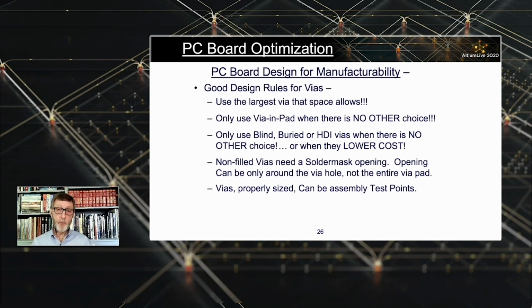We used to spend weeks after prototyping putting test points in really high-density boards at L3 because we knew that before we shipped that thing for final production runs we needed to have 100% test point coverage. If you can't do that, well, I'm sorry. You can't be guaranteed it's going to function. Is it costly? Oh, man, is it costly to design those in? Do you want them to be producible or not? You have to decide.